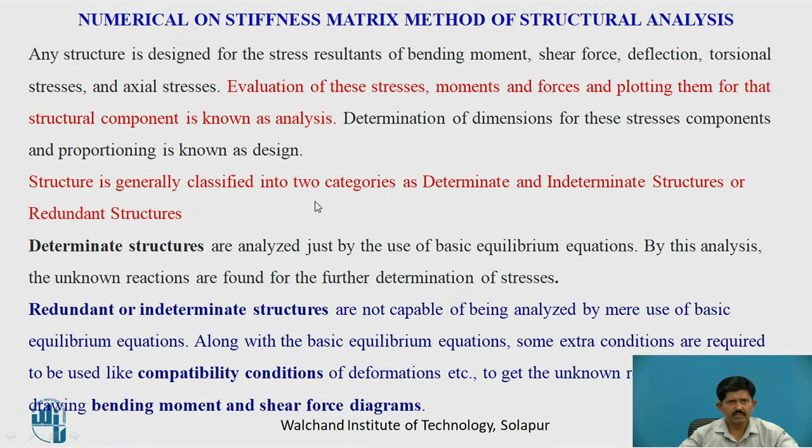Structures are generally classified in two categories: determinate structures and indeterminate structures. Determinate structures are analyzed just by the use of basic equilibrium equations. By this analysis, the unknown reactions are found for the further determination of stresses. Whereas redundant or indeterminate structures are not capable of being analyzed by mere use of basic equilibrium equations. They need some extra conditions like compatibility conditions of deformations to get the unknowns.